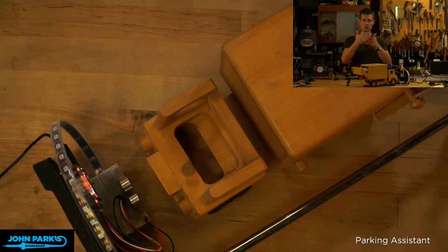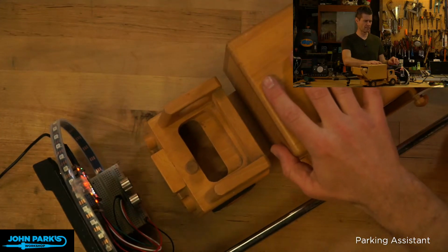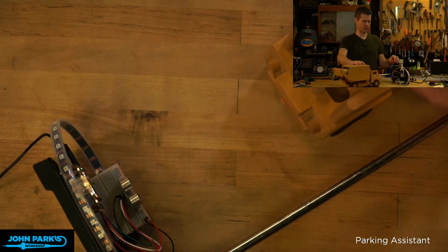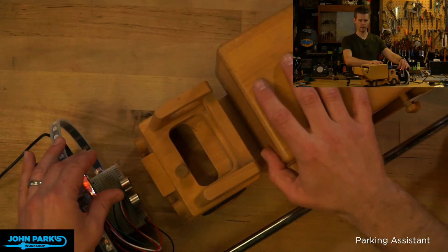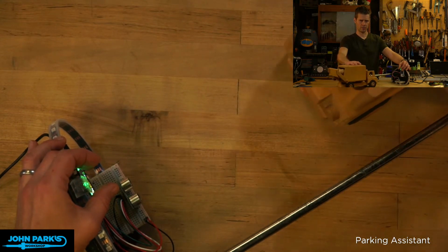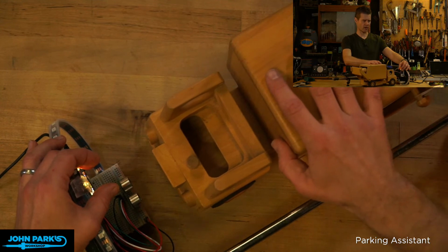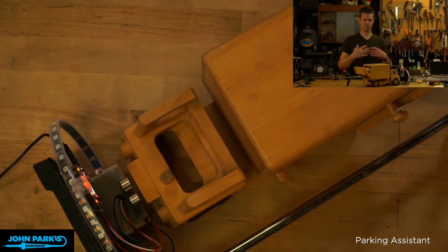So you could tune those values. That's all I did, I just kind of held my hand over it while I was coding it and set up some numbers. I think 20 centimeters is yellow, anything beyond that's green, and anything closer than 5 is red. So you can see as we back out, we get a little change in that light there. Put my hand there so you can see the reflection. There we go. And so this is just my first sort of prototype version of this.